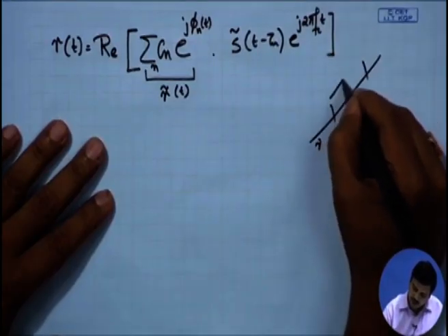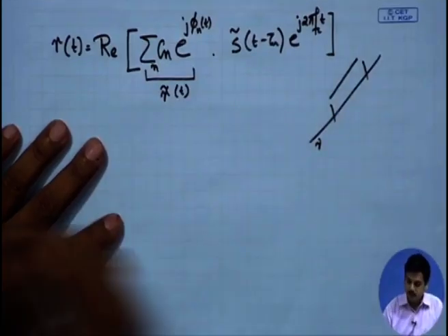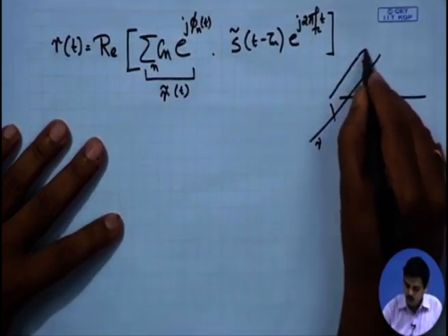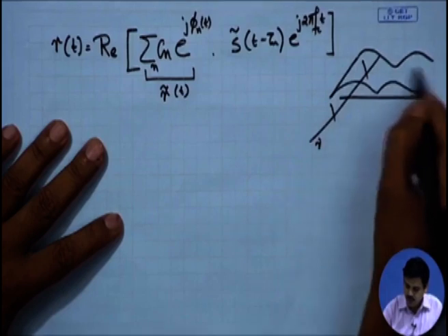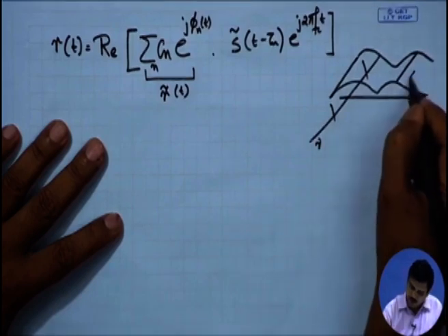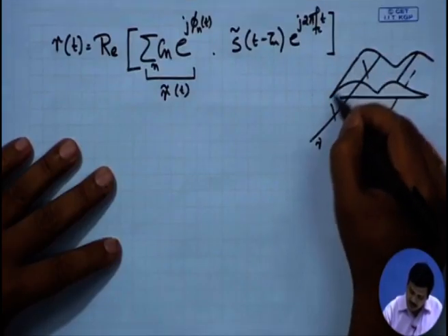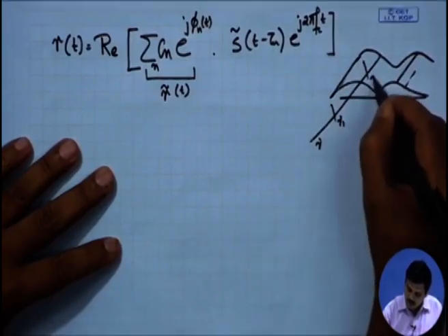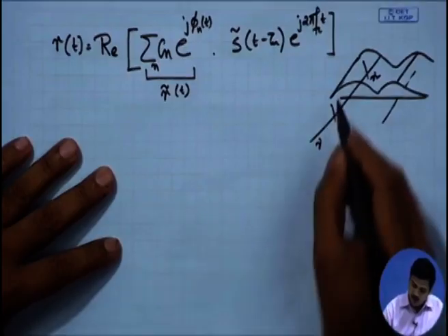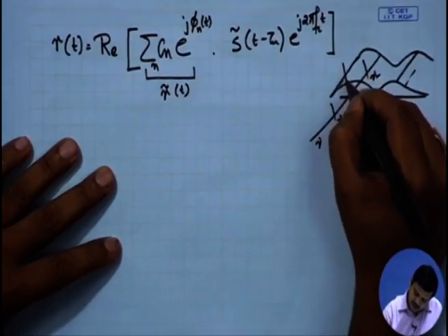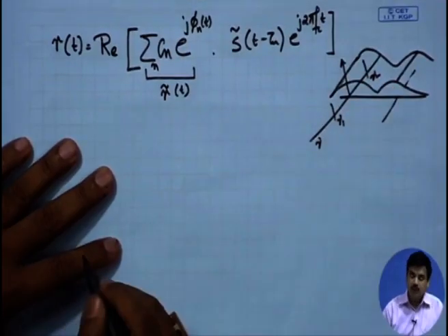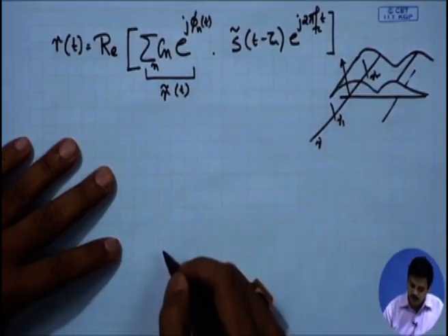flat fading is one wherein the entire range of frequency the gain is constant, although the gain changes with time, with the same gain remaining across the entire frequency. Now, since the gain is flat across the frequency range of interest, we can study it by sending a single tone in the whole band of frequencies.